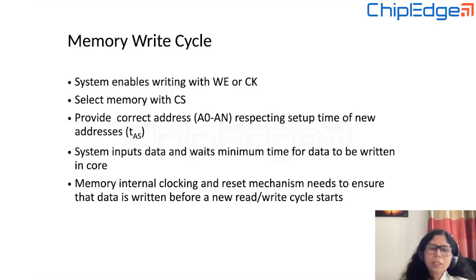And again, the internal clocking and reset mechanism needs to ensure that all the default signals, all the reset mechanisms are taking place, the bit lines are precharged, the bit lines are off, and everything is ready for the new cycle.